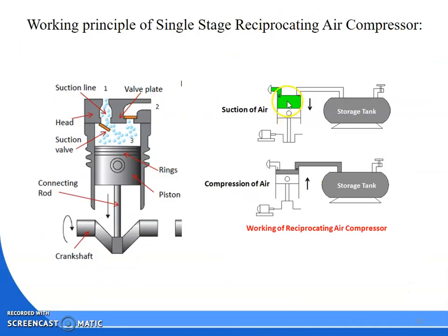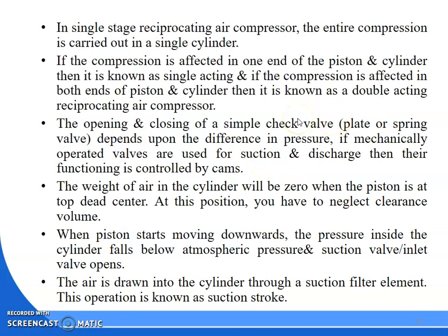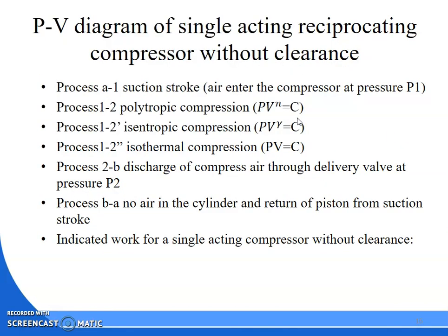So if you see the diagram, there is no clearance. What is clearance? When the piston is at top dead center, the gap or the space between the cylinder head and the piston head is known as your clearance. So here we are not considering any clearance.